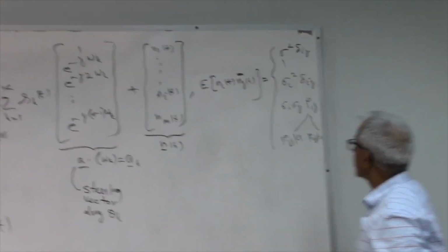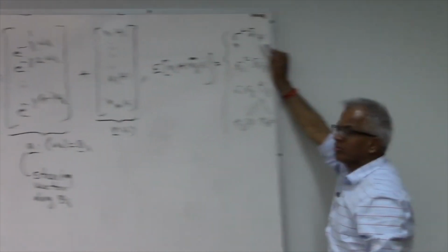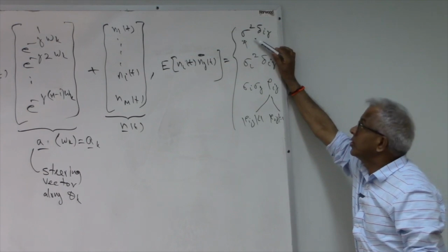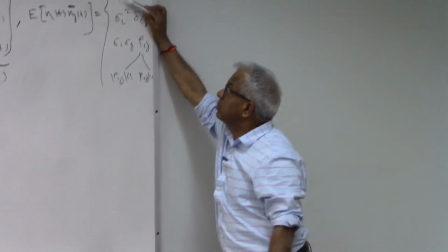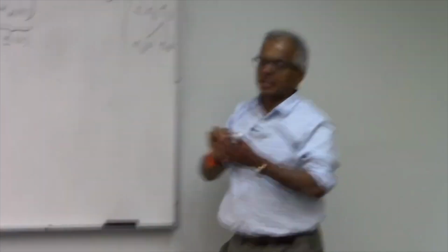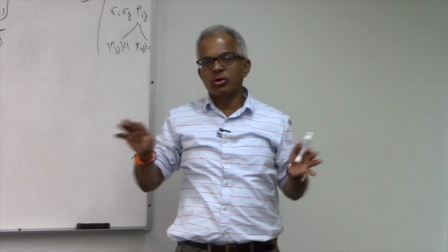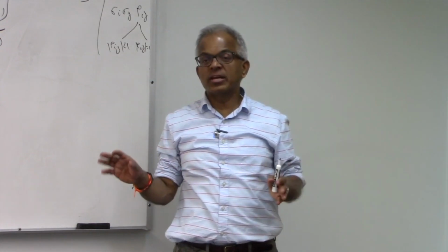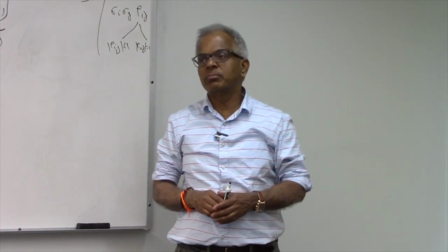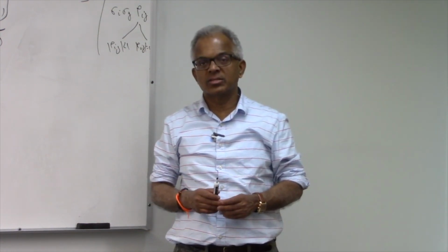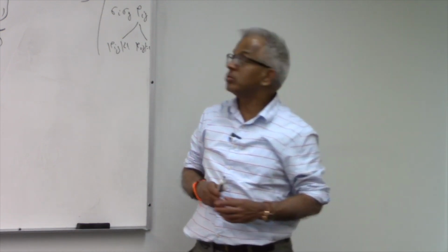All right, so 4 different noises. The ideal case is the easiest one, which is what we will deal with today, when the noise from sensor to sensor is uncorrelated but has equal variance. The logic here is that sensors are not miles apart, right? Sensors are close by, so the noise situation is similar, but they are sufficiently far apart that each sensor is not being influenced by the other sensor. Like crossover, etc., is 0, right?